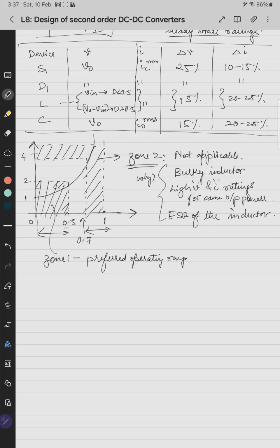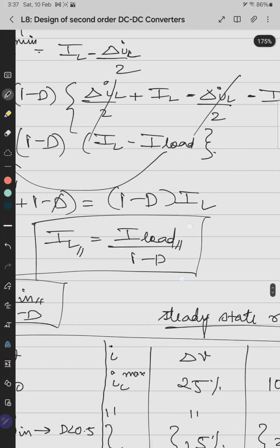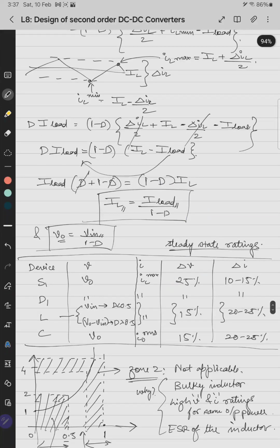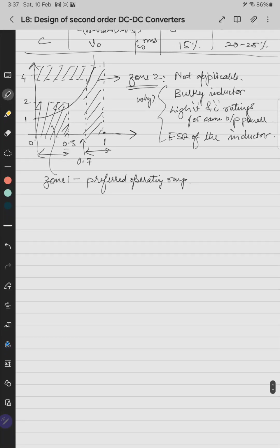That is the reason. For a boost converter, say it is a 1 kilowatt application and the input-output voltage gain V1 by V2 is 10 is to 100, then the current will be 100 is to 10, because we saw the relation. It is an inverse relation between the currents. So it will be 100 is to 10.